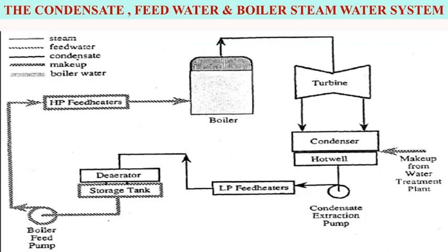In a thermal power station, the feed water system is made up of different parts like the deaerator, boiler feed pump, piping from the deaerator to the boiler, then the feed water supply system within the boiler, then steam passages. The water passage also includes the economizer, then downcomers, then water walls where the water-steam circuit part is, then the superheater and reheaters.